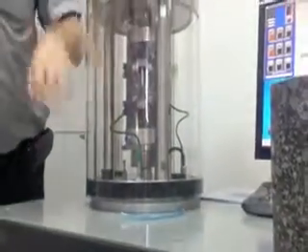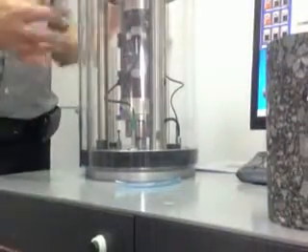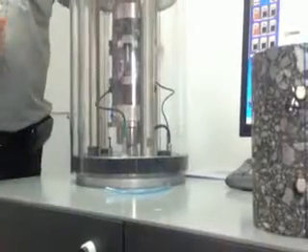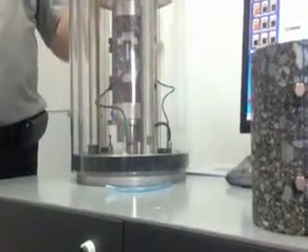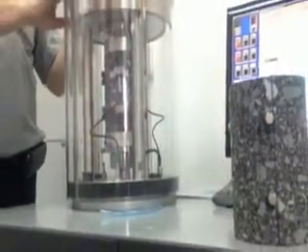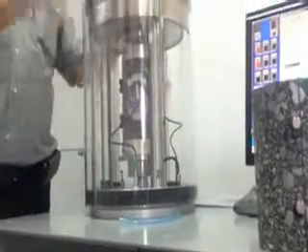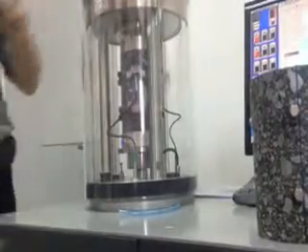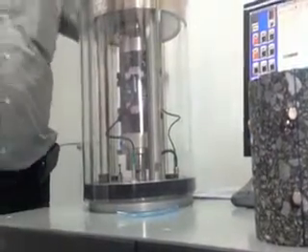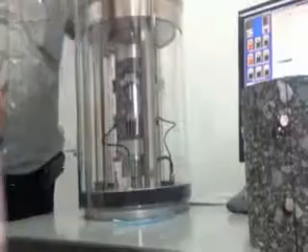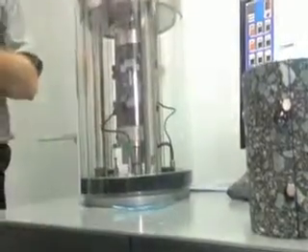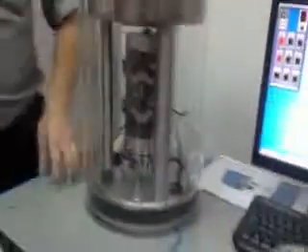It's rated for 400 kPa for the chamber. There's a relief valve here which will relieve any pressure in excess of 275 kPa. So the chamber's overrated, but this will blow out. It opens automatically; it's a little hard to see there, because it's a safety relief valve.